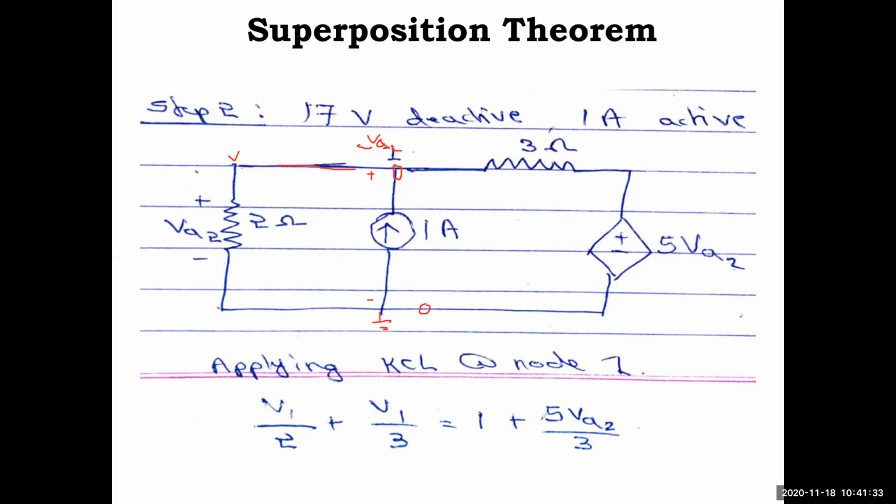So if you write the KCL, and again also I have written straight away. So you have three branches here, this is one branch, this is one branch, and this is one branch. And as an assumption, in node, what we'll do, current is always leaving the node, we will consider. Current always leaving the node. So with respect to that, now if we write the KCL, so VA minus 0, so this is going this side now. So VA minus, I will write a separate equation and then you write that. So the straight away written equation, that VA minus 0 divided by resistor.